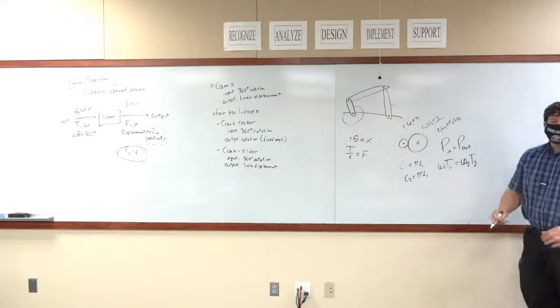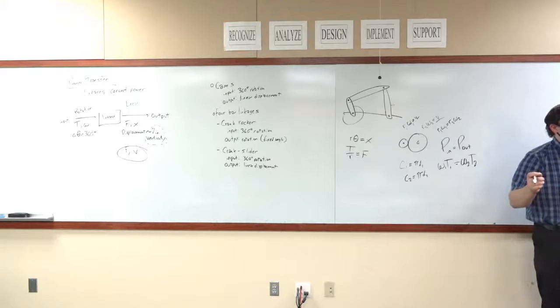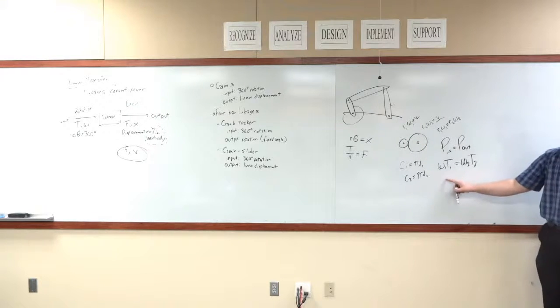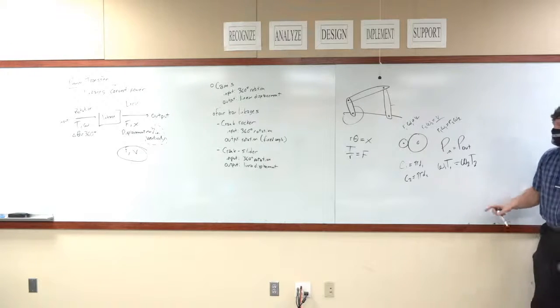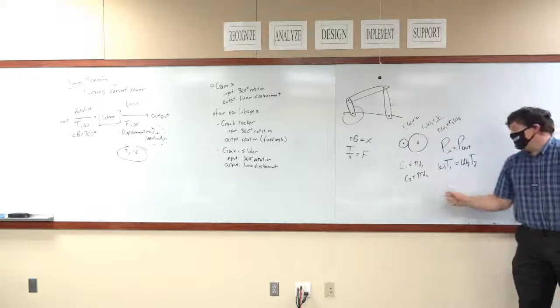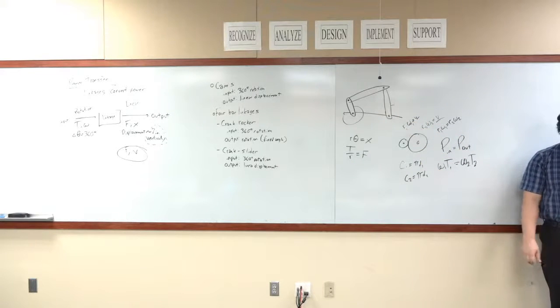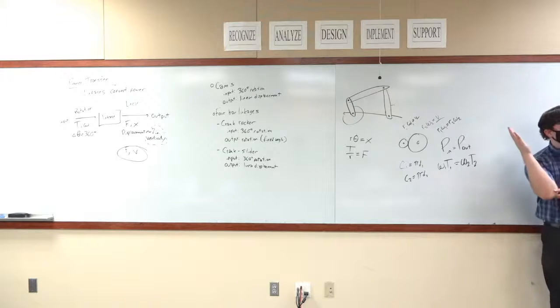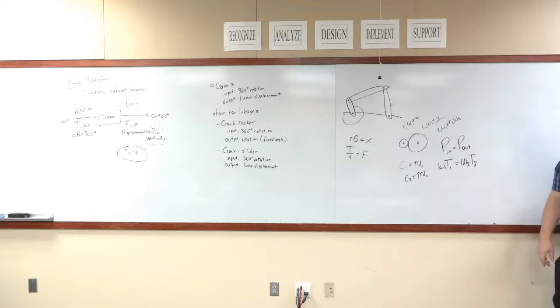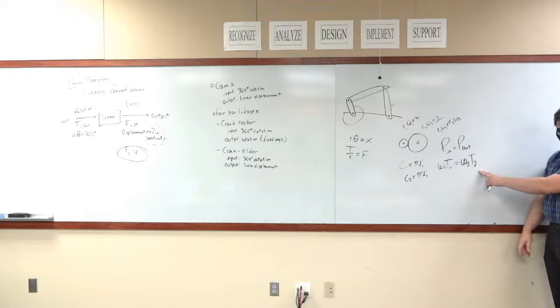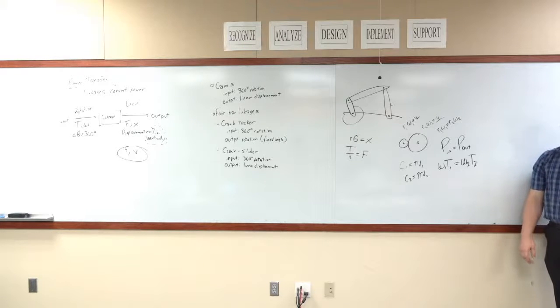Now, when I said that 4-bar linkages have unique timing attributes, this is true, but these change dramatically. At some point in your rocker mechanism, your omega equals 0. Because it stops, it reaches its maximum displacement. At that point, your t value is infinite. So, pretty cool feature there, having infinite force translation.